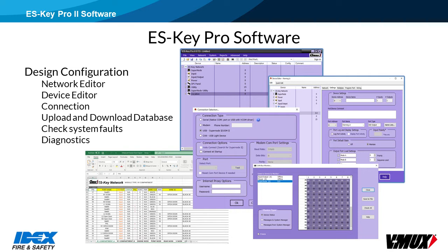The device editor is used to create and configure ports for devices created in the network editor as well as to configure certain features for special purpose devices. Each port can be configured. This includes naming, load manager settings, polarity selection, special program ports, such as seat belt and vehicle data recording configuration and multiplexing for all output ports.